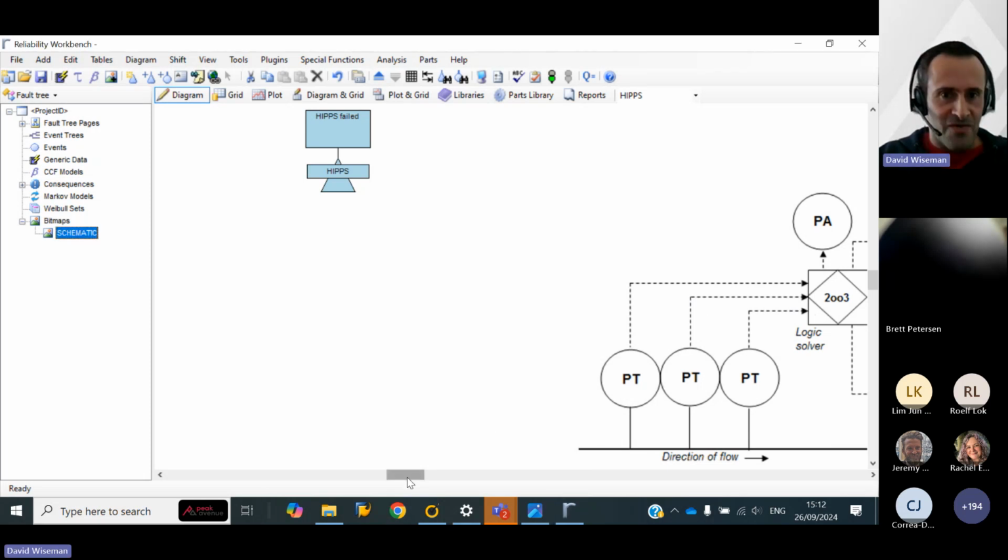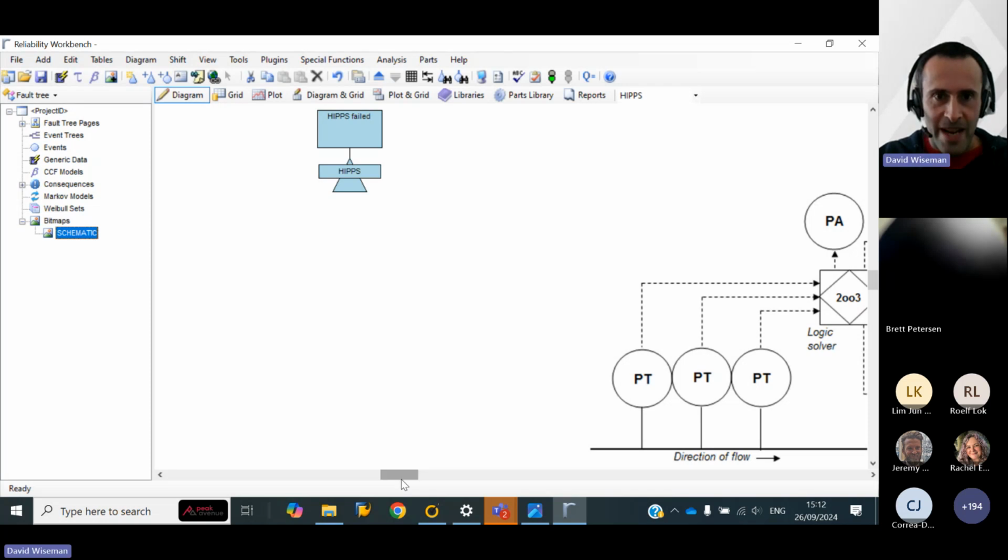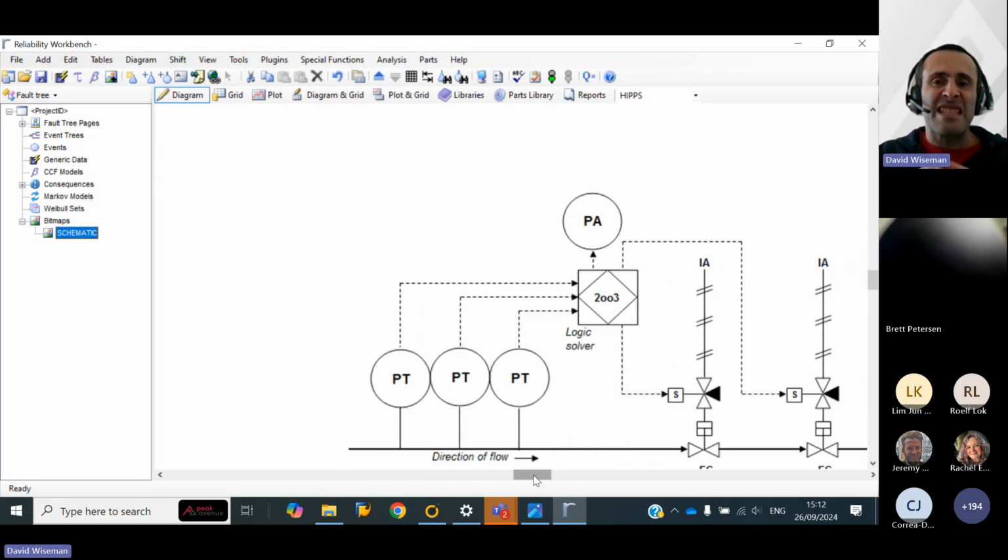So, okay, back to our FaultTree. Top gate, our safety system is in a dangerous fail state. Why would that happen? There are basically three fundamental elements to our safety system: the sensors, the logic solver, and the final elements. If any one of those three aspects of our system were to fail, we would not be able to respond to an overpressure. Any one of those three problems would result in a dangerous failed state for our system.